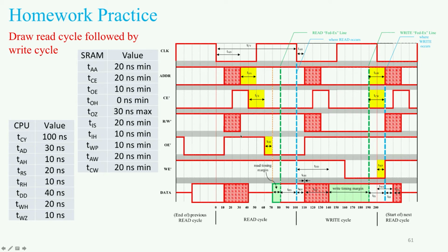Okay, so that's what initiates the final phase of the read. So the first phase, the lower half of the clock, you've got the CPU setting up the address, you've got whatever happened last time potentially getting off the bus, you've got these bits being set up correctly, and then once the clock flips high, we're going to start toggling these bits that control the SRAM. Remember they're dependent on the clock signal.